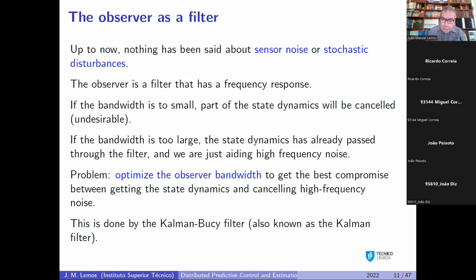And then you have a noise which is white, that is to say, it appears with an equal power density all over the spectrum. White noise is a noise that is constant from minus infinity to plus infinity in frequency. In many cases you don't have white noise, but you have wideband noise.